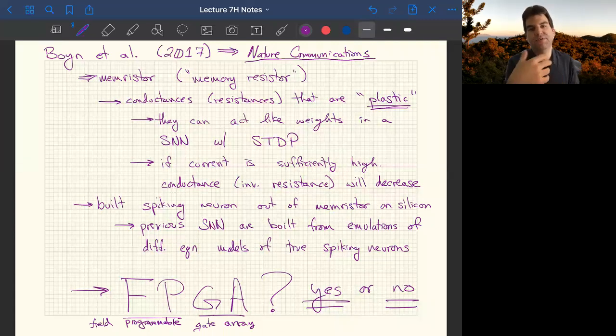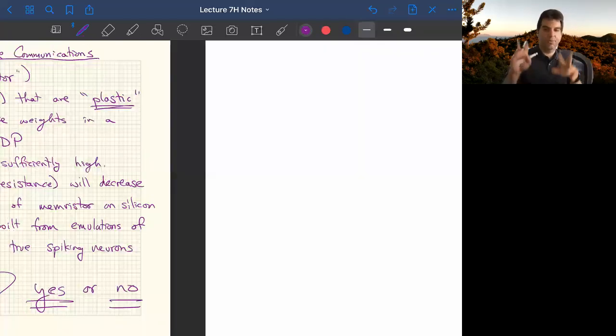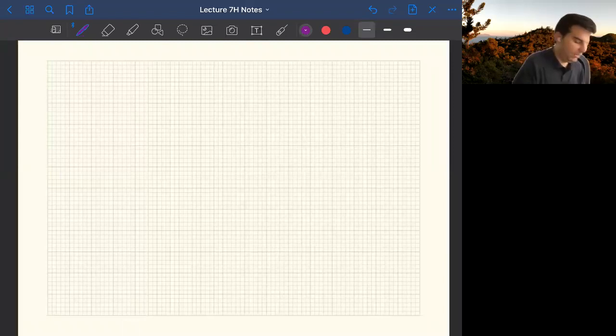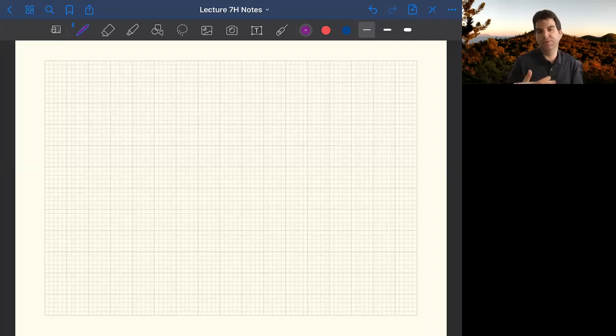And so it provides you a way to download a logic circuit to an FPGA and then reprogram that logic circuit in the field. So you don't have to find a new NOR gate and pop out your NAND gate and put the NOR gate in. You can just change what's shorted together and what's opened, and that'll change all the input-output maps. So this idea of arrays with crosses has been very helpful in building hardware that can do things in a very flexible way.